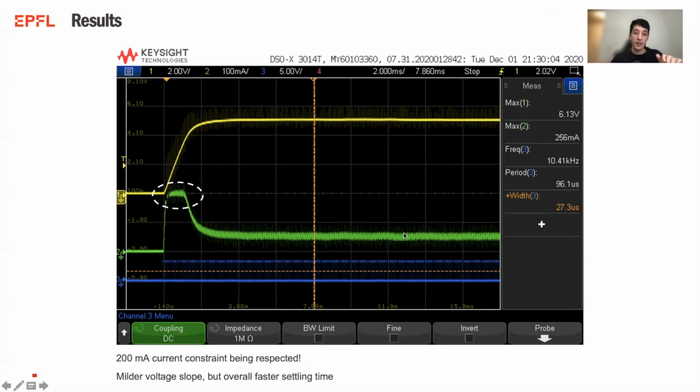Just for the record, a smooth startup could also be achieved with a very simple hand-tuned PI controller. That would take maybe 5 hours to code, a very simple one. However, a PI controller would be very much slower when compared to MPC. It would be 20-50 times slower. MPC shines because it can go fast and respect the constraints. This is its strength.